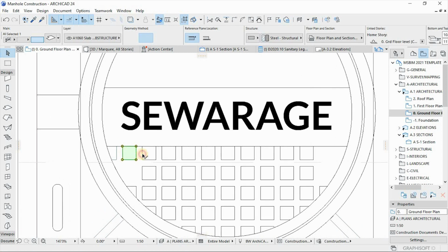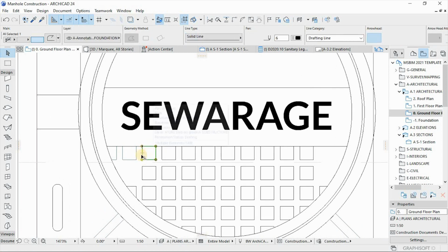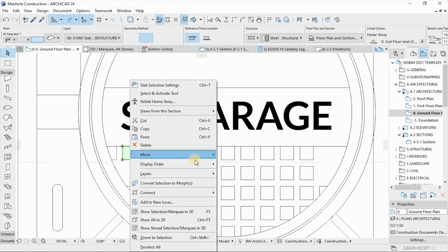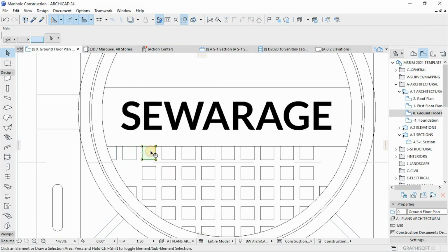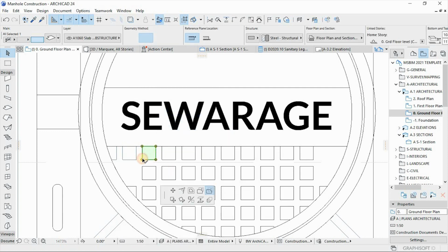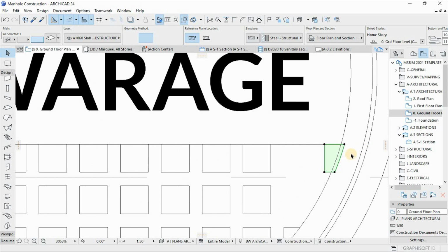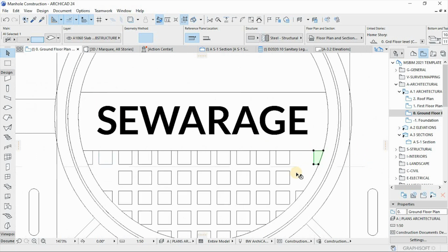And then I would do the same to duplicate along this. But before I do that, let me just copy this to that side, or mirror it to that side by Ctrl+Shift+M as a shortcut. Then have something like that. It can be that way.